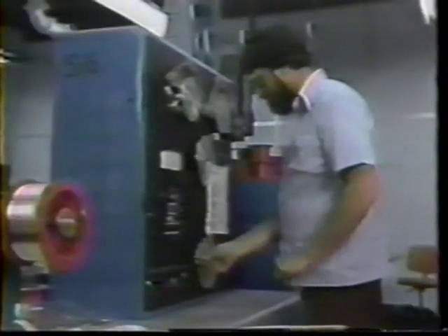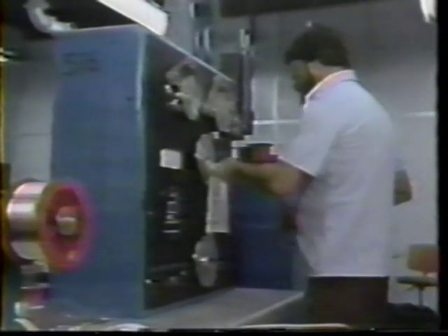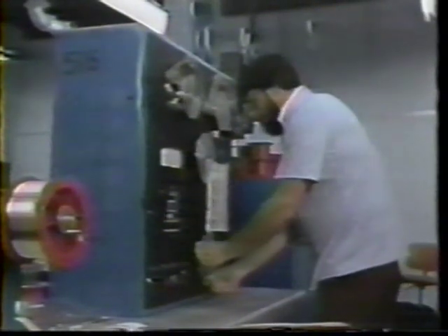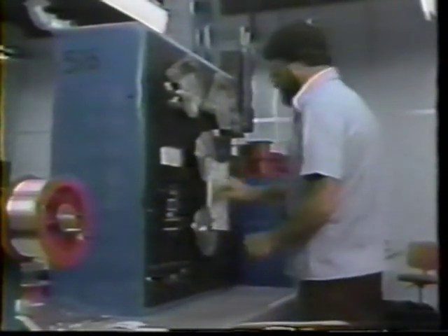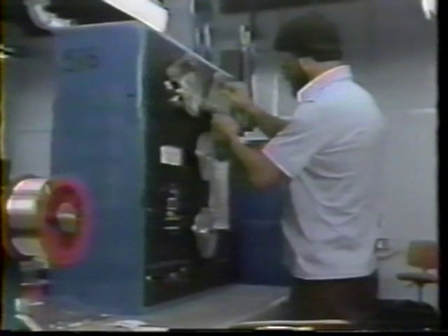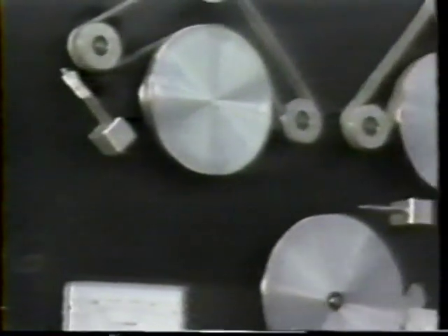As a last step in the drawing operation, every section of fiber is proof tested for strength. This might range from 50,000 pounds per square inch for standard multi-mode fiber on up to 200,000 pounds per square inch for single-mode fiber laid on the ocean floor. The light guide must be able to withstand the stress of manufacture, installation, and of course service.